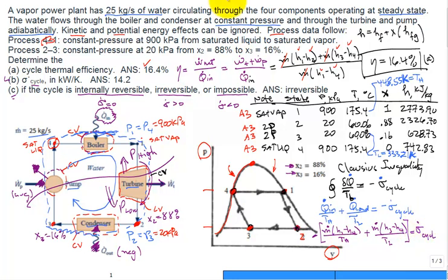All right, well, do I know the mass flow rate? 25 kilograms per second. Good, so I know the M dots. Do I know the H's? Yeah, we used them already for the answer for part A. We have the temperatures. Notice they need to be in Kelvin, and if you look at the units, what's the unit right here? Kilowatts per Kelvin.